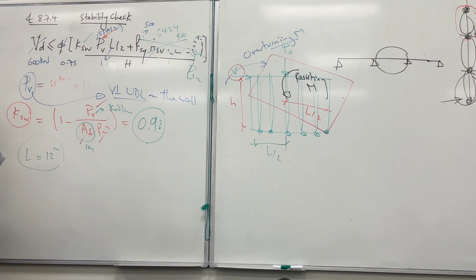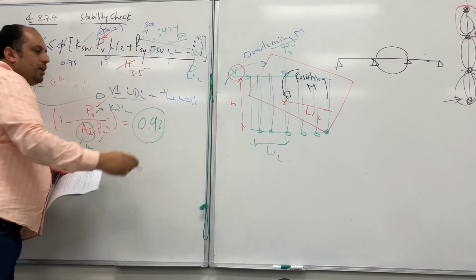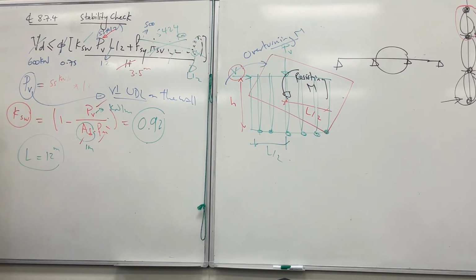So have you calculated what h is? What is h? Height. How much is the height? 3.5. Yeah. Okay. Have you taken it as 10.5? It is not 10.5. It is 3.5. This is a question to you: can it be 10.5 here? Do you think the force can rotate everything, even with the slabs and the columns and so on? No, you will restrain the wall again from the slab. So it cannot be considered as one wall.